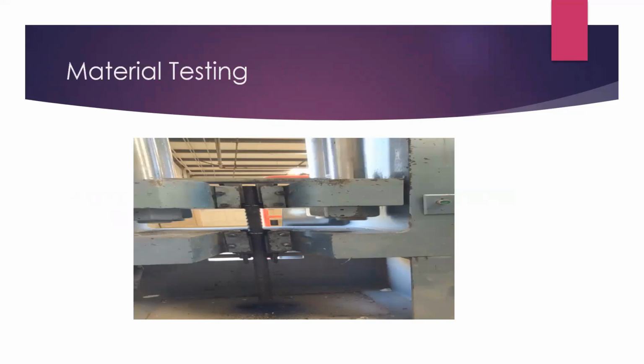This is a very large piece of rebar. I want to say he said a number 11. So first of all, rebar is the stuff that we put inside concrete to give it tensile capacity. And it's a steel material that has, you can kind of see, roughness on the sides. It's not a smooth bar. That roughness helps it to interact with the concrete to get kind of grabbed by the concrete so that it doesn't slide. And they have to test it to make sure it has the right tensile properties.